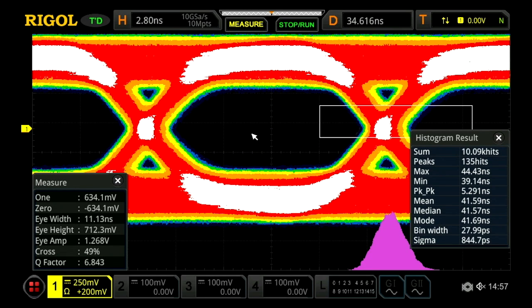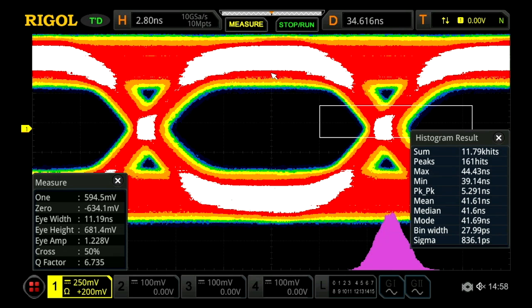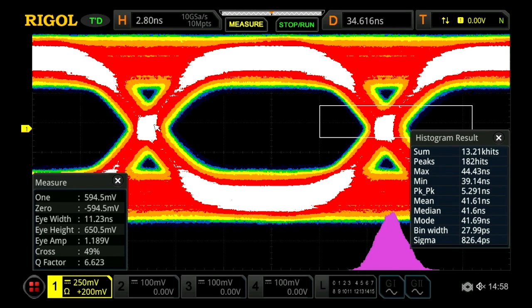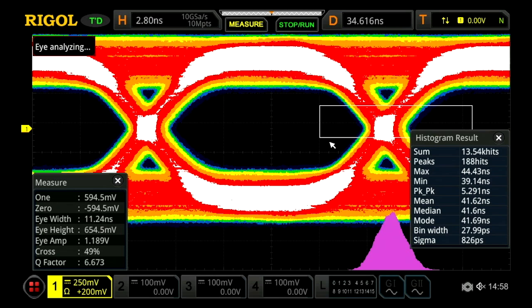We can actually see in this eye diagram there are a couple different issues impacting our results. One, we see vertically a lot of space here. This implies a certain amount of noise coming through the signal that might be affecting our ability to get a clear bit test at this point. Additionally, the rise and fall time on these transitions are pretty diagonal at about 45 degrees. In these settings, we'd like it to be steeper, giving us clearer corners in this eye diagram. That's likely a bandwidth issue, not allowing the signal to change fast enough.